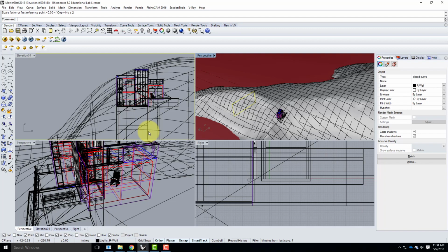There is another command that I have not talked about yet, but I'm going to talk about extensively in the next 3 days, that I think takes Rhino from being a really awesome 3D program to being far and away the best 3D program available on the market because of this one command. And this command is called Make 2D. Any view that you have in Rhino, perspective, elevation, section, plan, whatever, Rhino has a command called Make 2D that will take that view and convert it into a set of line drawings. So whatever the perspective view is, it'll make a 2D line drawing for you, which is absolutely fantastic. We're going to use that here in the elevation 1 view.